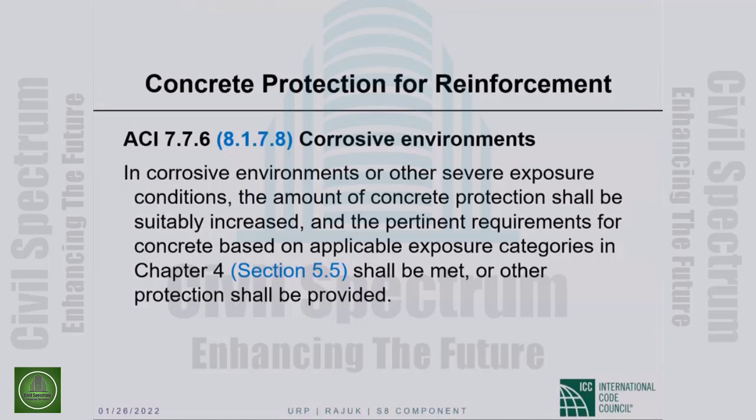Now, corrosive environment, definitely very, very important for many parts of Bangladesh. In corrosive environments or other severe exposure conditions, the amount of concrete protection shall be suitably increased. So we are saying that the values in that table shall be suitably increased. Obviously, it is not very specific.